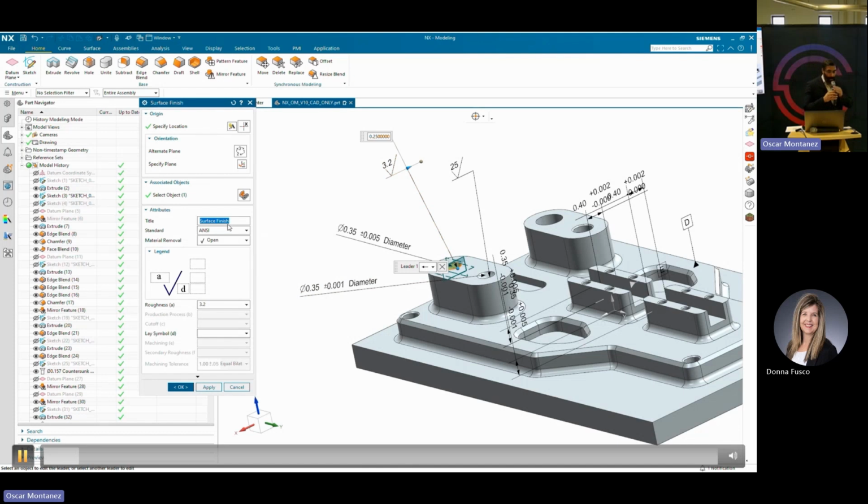Okay, and now with the surface finish call out, you can see that if you were to put on the surface finish call out and you wanted to put a roughness measurement, the A value here, you would choose either something in the list or type it in. But typically the way that this call out works is you have to put RA space the value. As it stands, that's not consumable. The way that we force it to be consumable is that we get rid of the RA